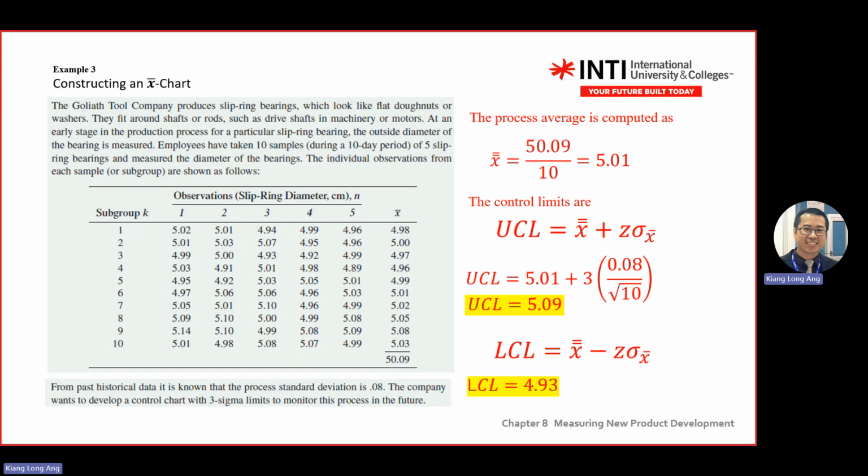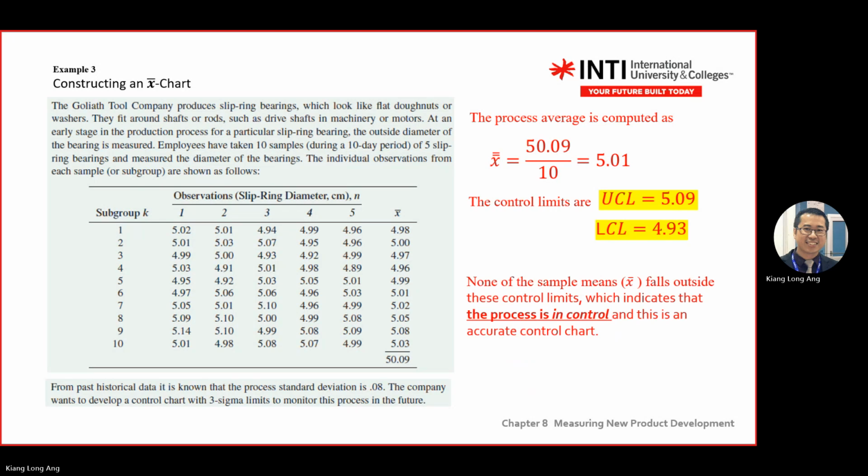Then for the rest, you start with the graph on the y-axis and x-axis, then plot your mean, draw the mean line, draw your upper limit line and lower limit line. Then after that, you can observe from the table or from the graph. So here, from the table, you can already observe that your upper limit is 5 something and lower limit is 4.9. You check the average here. The average here is between 4 and 5. So this one, all the data is in control.